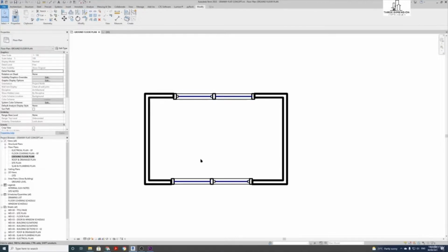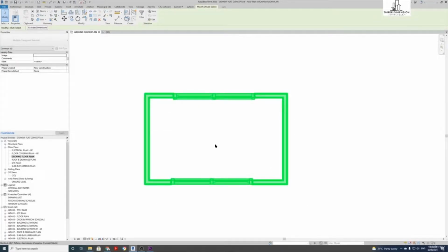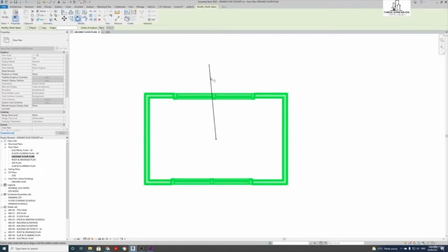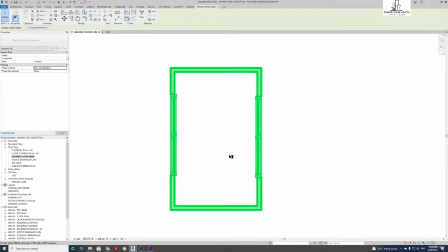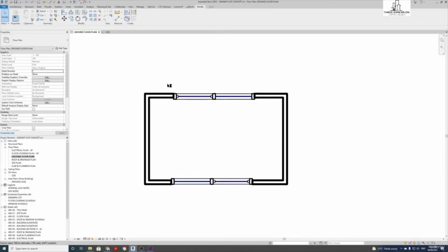So there's lots of, just giving you an example of another one. If we use our selection tool again, to select everything here, type RO, this will bring up the rotate tool. To use that, click wherever you want on the screen, then rotate it around, and that'll rotate in that direction. Yeah, so another example of a quick keyboard shortcut is to rotate.